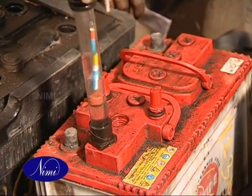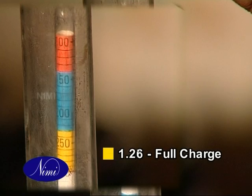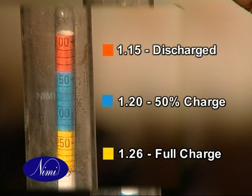These are the hydrometer readings for various cell conditions. Fully charged, 1.26. 50% charge, 1.20. A discharged condition gives 1.15 on the hydrometer. In case of nickel iron cells, there is no appreciable change in specific gravity between charge and discharge condition.